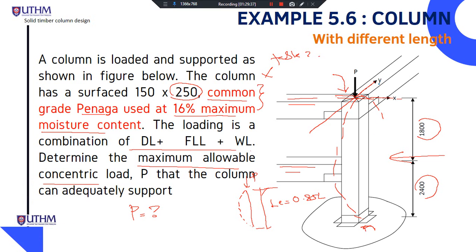Meanwhile, for the y-axis here, the buckling tends to buckle in this shape. So we have one here. You see, this is the first restraint, and this is the second restraint due to the pin position. So it has two buckling shapes, like this.